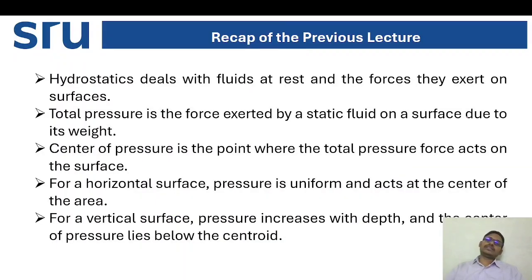We'll see the recap of the previous lecture, then we'll go with the other thing. We have discussed hydrostatics, which deals with fluids at rest and the forces that are exerted on surfaces. We have seen the total pressure as well as the center of pressure for a horizontal surface and for a vertical surface. Pressure increases with depth, and the center of pressure lies below the centroid.